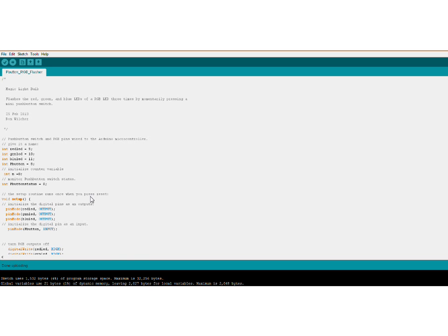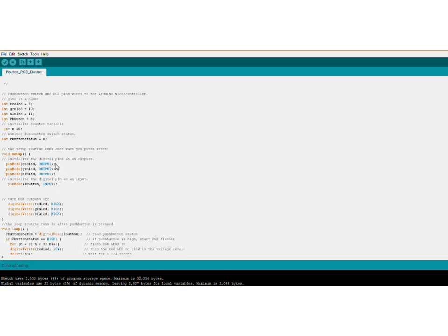So the next thing we do is the setup, and the setup is where you really define how it's going to be built. So I have what's called the pin mode, and what the pin mode explains to the Arduino is, hey, I've got these three LEDs, and I want to make these pin numbers, which you see here, 9, 10, 11, and we have the names associated with them, but I want those to be outputs. So again, going back to that block diagram, it's about the inputs and the outputs. The inputs are on the left side and the outputs are on the right side.